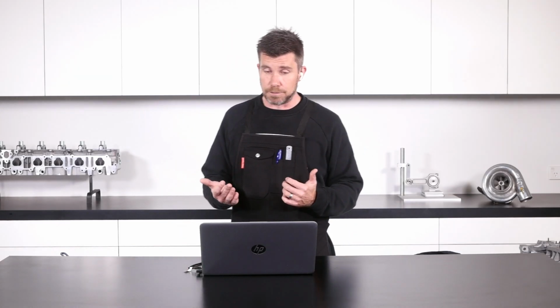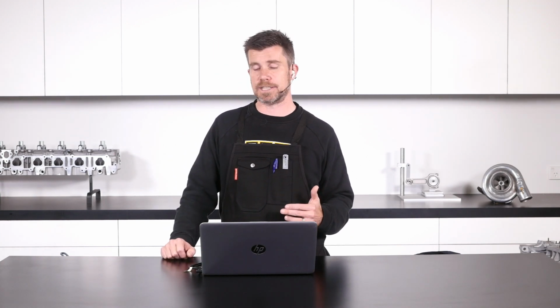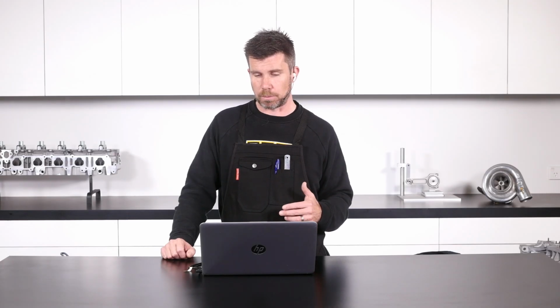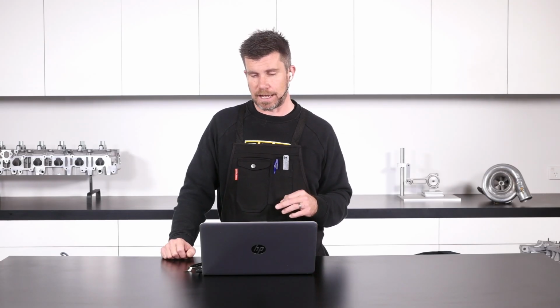Look, for a start, I would say that you're getting a really good result if you are only just equaling your boost pressure at peak RPM. And given that your usage is hill climbs and street, I would definitely think that trying that smaller housing would be probably quite a good idea. You might find that you'll sacrifice a little bit of high RPM power because your exhaust manifold pressure is going to increase. But yeah, a lot of people fall into the trap of thinking that power is the key component that we're chasing, but it's really not.